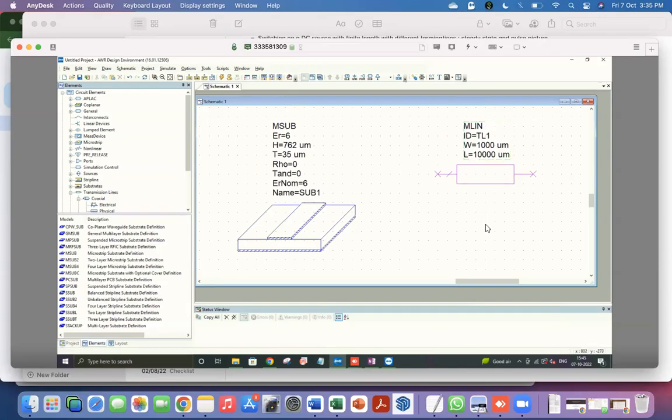Any ideas? Yeah, but what should I measure? So there are a couple of possibilities. I could do a 2-port simulation, or I could do a 1-port. So if I put 1 port here and I put a 50 ohm on the other end, then if this was a 50 ohm transmission line, you should get no reflection, right? If it is not a 50 ohm transmission line, then you will get reflection. So we can then adjust the parameters till we get no reflection or very small reflection.